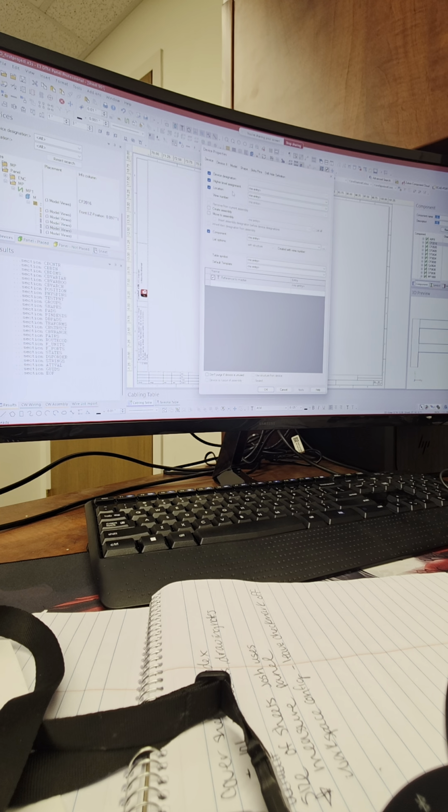In these attributes that you see down below where it says reference to master, and then you have a blank field, in that blank field, let's just add a new attribute. You see a drop down menu that appears. The attribute that triggers something to be excluded from the BOM is called no BOM. So just go down to the no section, and there should be a no BOM option. And as a value on the right side, it's just a 1 or 0.